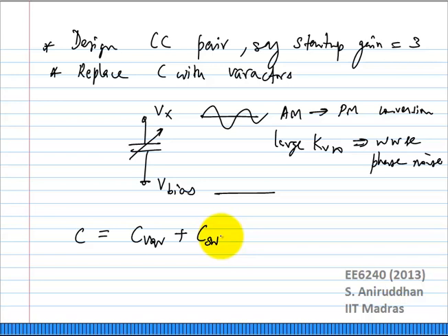To embed it inside a PLL, and the DC voltage of the PLL will control the tuning input of the VCO. Why do you need to control the tuning input of the VCO? Because fundamentally the VCO drifts due to voltage and temperature and the frequency changes due to process and so on, right? To tune it to exactly the same frequency, you need a PLL and you need a tunable voltage.